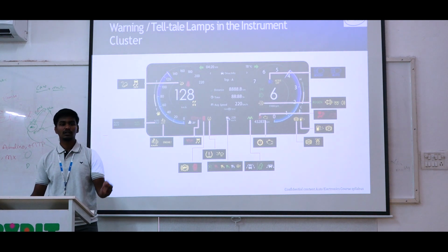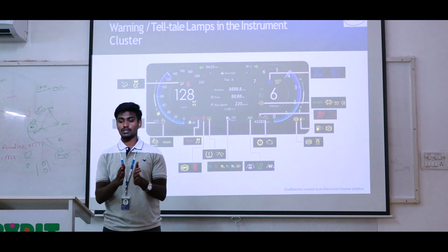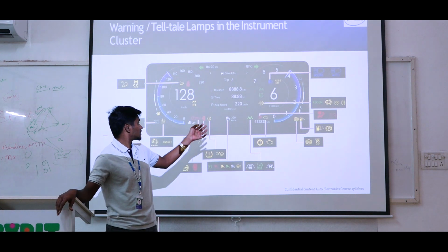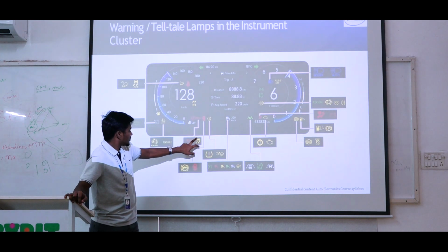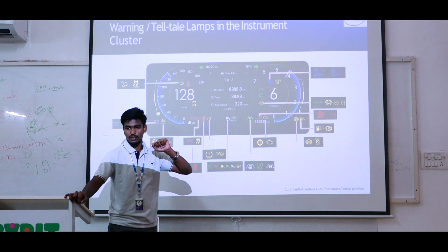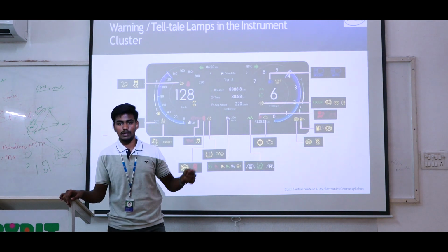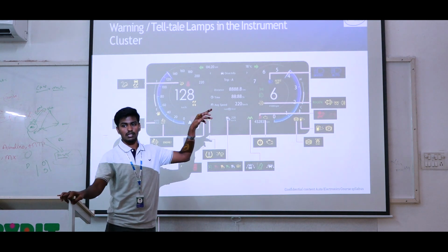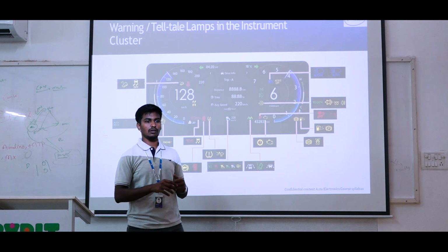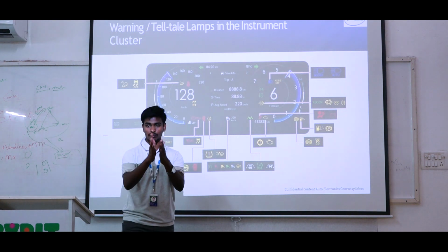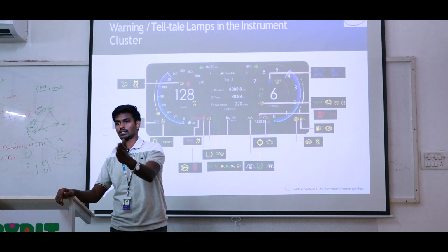Yes, like that. At the proper time of receiving messages, it needs to be checked with different kinds of ECUs. For example, we can take engine temperature. The engine temperature level we need to check with the engine ECU also. At the same time, it will be transmitting to the instrument cluster also. Based on these values, we can get it in the infotainment values also. If it is getting overheated, we need to indicate it to the driver system also. It is synchronous, at the same time: we need to get it with the engine ECU, then the instrument cluster, and then infotainment.